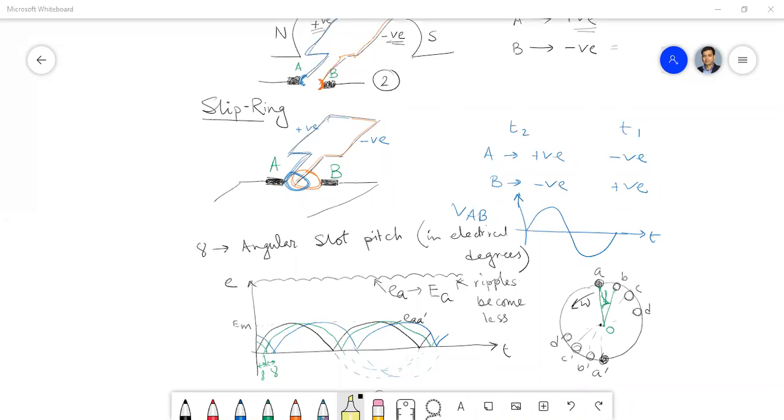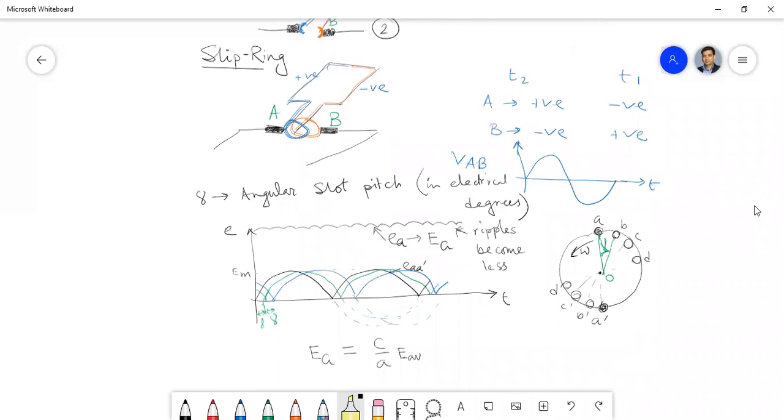Okay. Anybody else? Because every time it will remain the same polarity for slip ring arrangement. And so the direction of the current flowing in the coil will always be the same, a kind of direct current, that means DC. What kind of arrangement we need? Just slip ring. That means brush commutator is the wrong answer. You were saying that. Yes, sir. Okay.